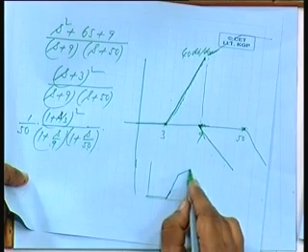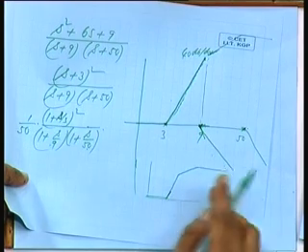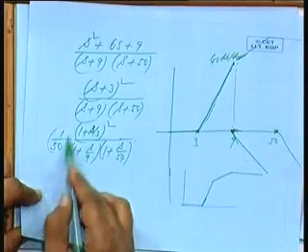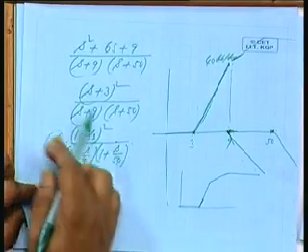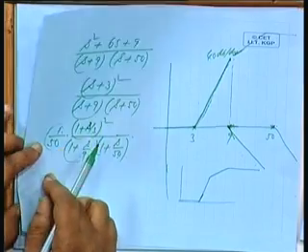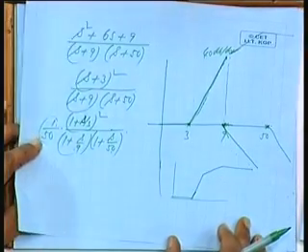So, the net function will look like 40 dB, 20 dB and then horizontal, and then depending on the constant 20 log of 1 by 50, it will be shifted up or down depending on its magnitude. Here it is 1 by 50, so it will be negative. So, it will be brought down by this factor, 20 log of 50.